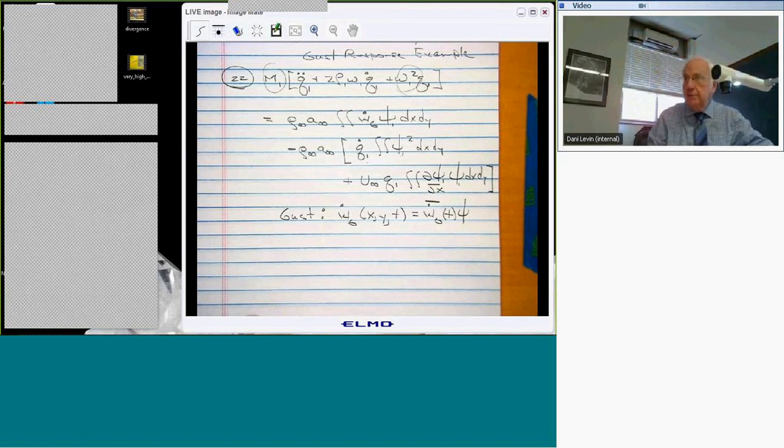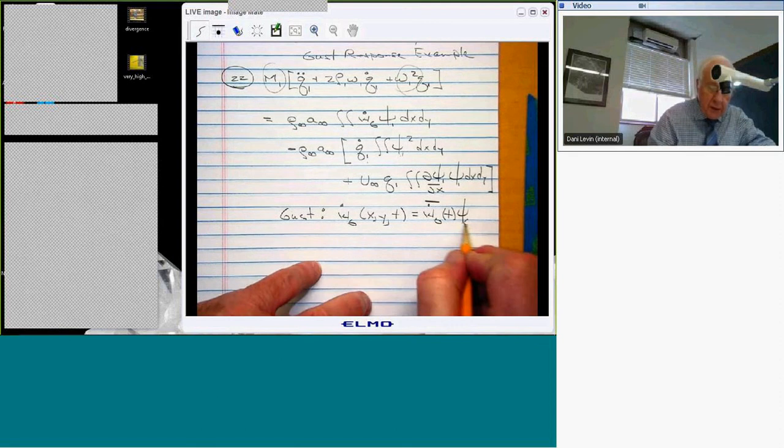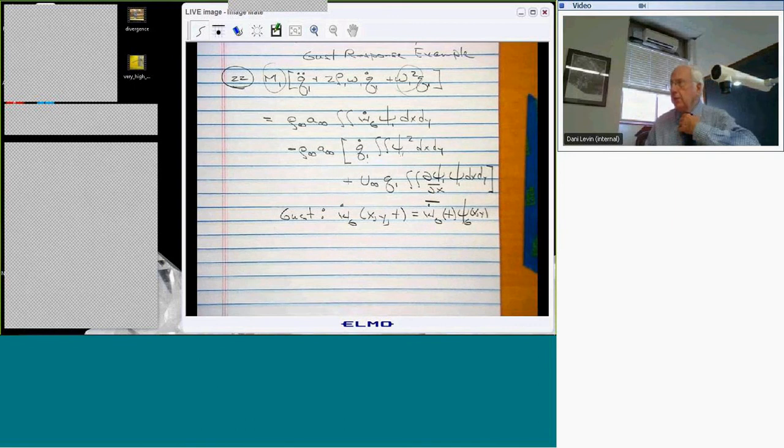Someone has to tell us that. And there are standard assumptions in the literature about what that should look like. But for our purposes, we've consulted a gust expert who's told us what this function looks like. Right? But now, because we want a transfer function, we are looking at simple harmonic motion in time. That's the great virtue of looking at transfer function. Simple harmonic motion in time, which simplifies everything in the sense that it's a linear system. The time goes away and it's replaced by a frequency, right?